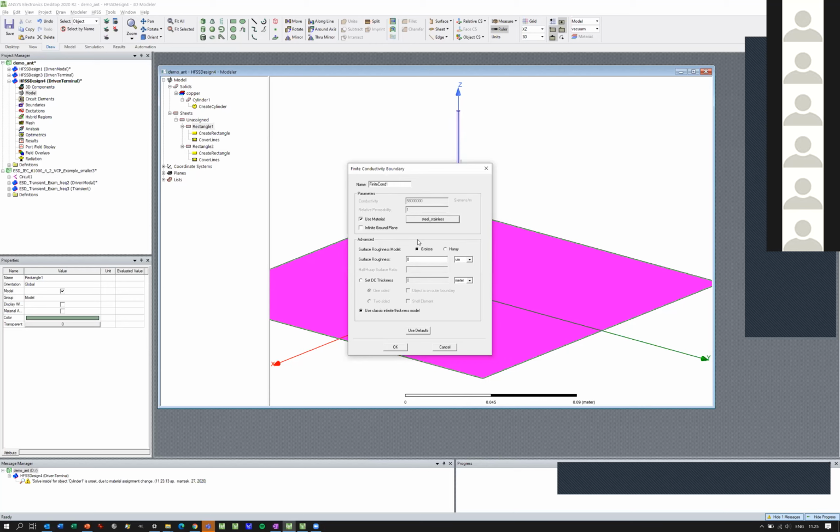When you go to really high frequencies, like 5G mobile phone, you really have to think about it, because the electromagnetic waves travel on the surface. Actually, it's a huge effect what kind of surface you have with the copper.